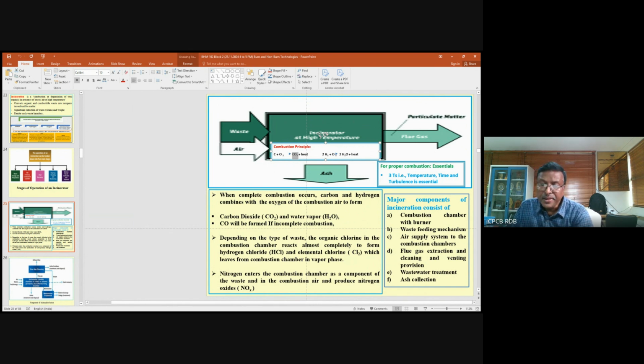That has to be cleaned before the gas is liberated into the atmosphere, through an alkali scrubbing solution, so that you can neutralize this hydrochloric acid. When it is neutralized and becomes free from hydrochloric acid, chlorine also can be removed. And because of these scrubbing actions of the alkali solutions, the NOx also can be minimized. And we can minimize the generation of particulates.